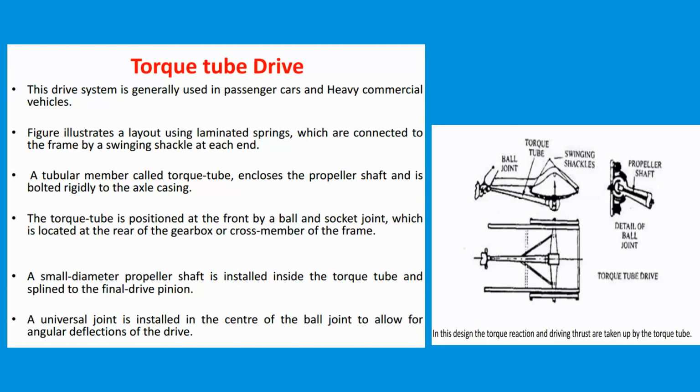Ford used less expensive transverse springs that could not take forward thrust. For many years, Chevrolet used torque tubes while Buick used them starting in 1906. The torque tube was also allowed, beginning in 1938, to use coil springs for a softer ride, unlike the traditional leaf spring, which can be used in a Hotchkiss drive, but coil springs cannot.